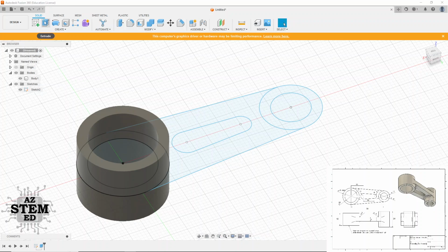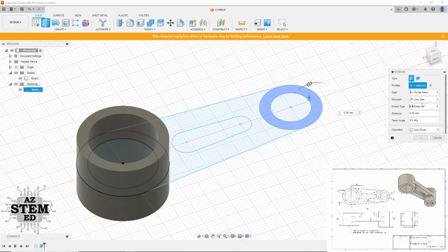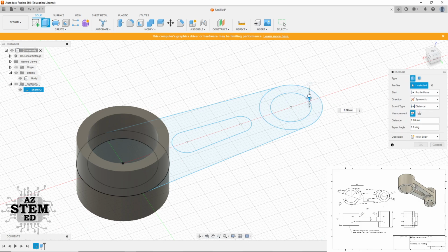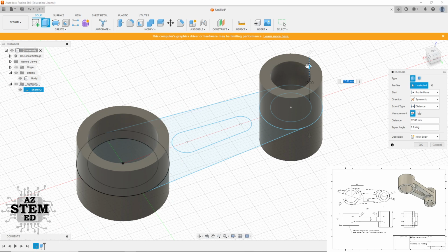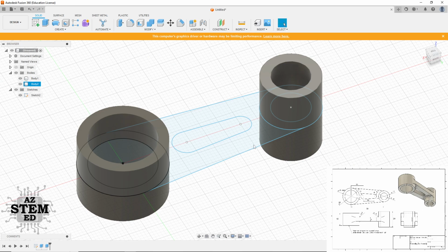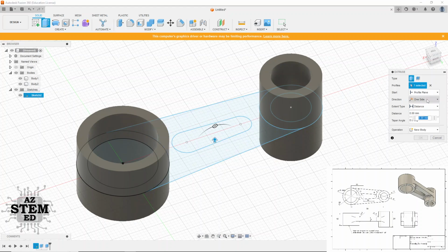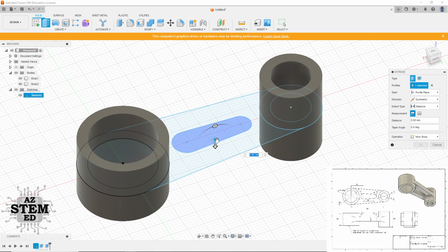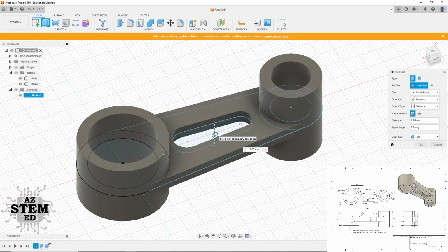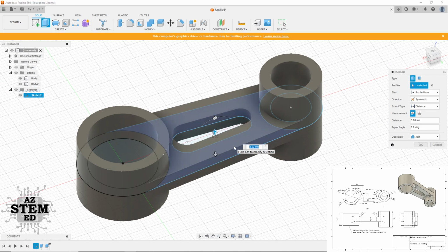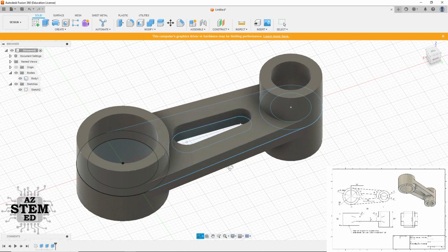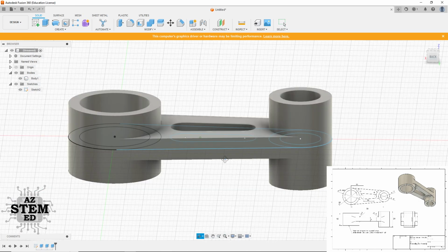All right, now let's do the extrusion on this side. Needs to be symmetric. Drag it up, and this distance is 24, so we need 12 as halfway. Okay, now let's do one more. Let's extrude this body symmetrically and push pull it. This distance should be 6, so we're going to go halfway, and that's 3. Excellent.